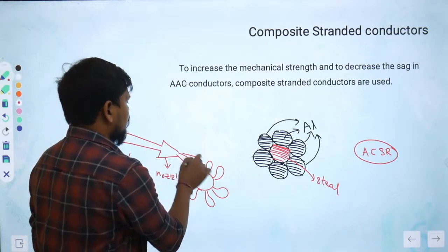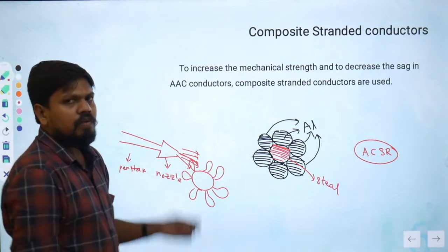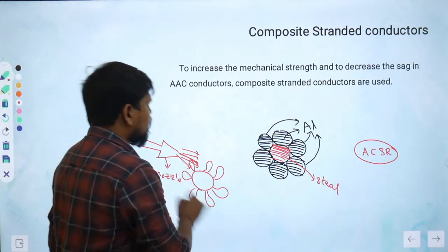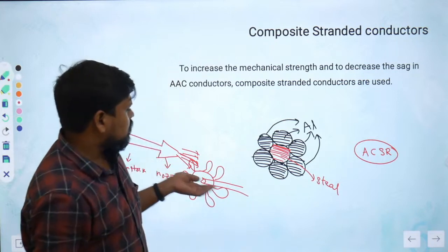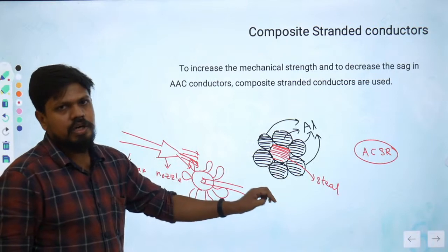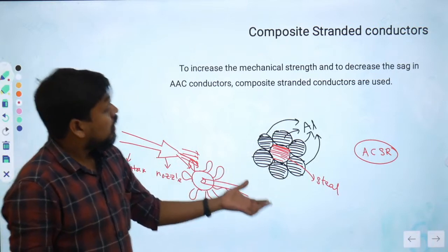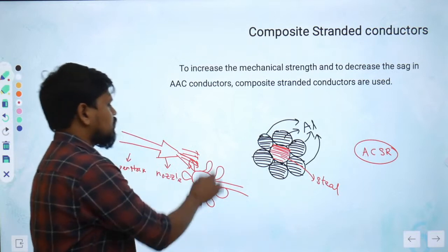Water flow will be hitting on these buckets like this. Got it, right? Whenever water flows, the turbine will rotate because of the pressure it creates. Using the same shaft, the generator rotor, a synchronous generator basically, will rotate, and that will give the power generation. That part I am not explaining, this one we will take.